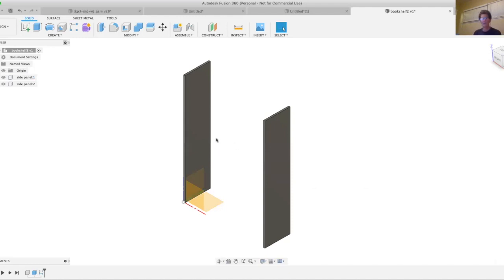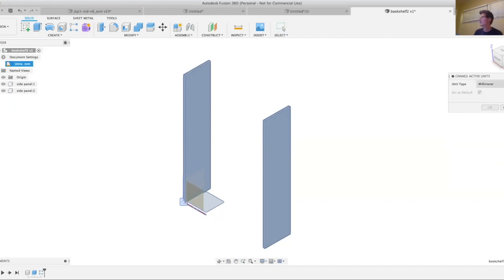By the way, I'm starting to realize that all the wood around here is in inches and feet, or what other people from other countries call archaic units. So I'm going to change the default for this drawing, active units, to inches, just to make this easier. Halfway through the design, no problem. I'll do this because sometimes I'm working with parts and I have some parts come in that are metric and some parts come in that are an inch. And I'll just be able to switch back and forth between them. So it's easy to do.